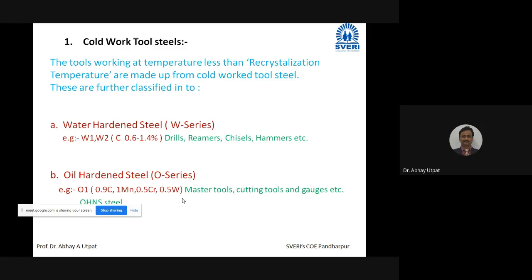Okay, no problem. I will consider your attendance. So friends, we can make the steel hard by hardening process. So in hardening process, part is heated at some particular temperature, hold there for some time, and then quench. Quenching is fast cooling. So you might have experience. You can make any part red hot in any of the flame and immediately dip into water. You will find it will cool immediately. So this is the process called as hardening.